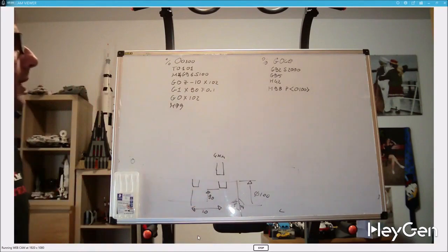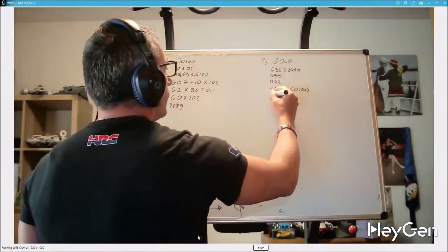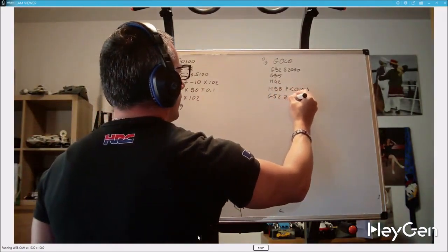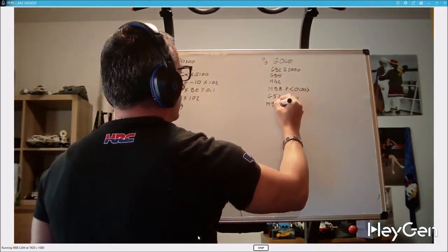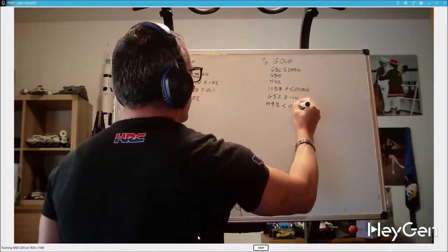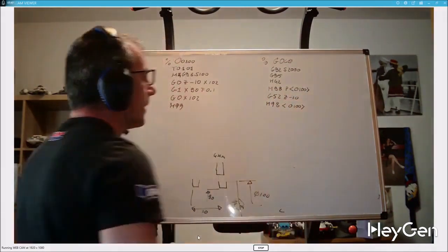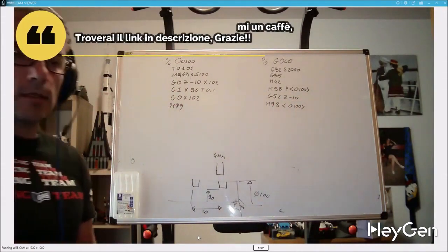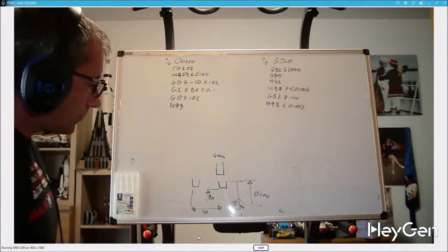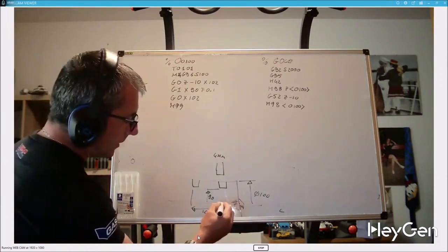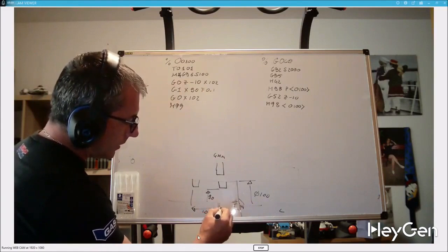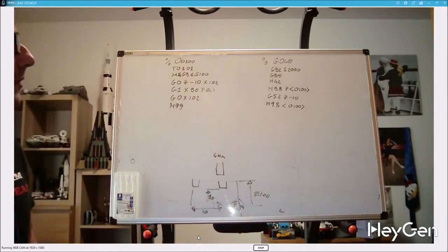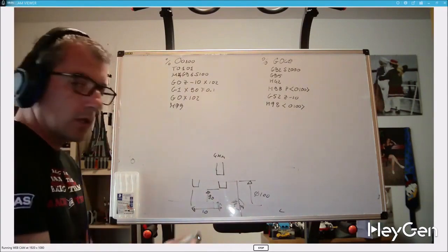So I use a function called G52 Z10, then M98 P0100. G52 Z10 is the translation of the origin. In simple terms, this origin is taken and moved 10 millimeters for the machine. The origin is no longer here, but is now 10 in the negative Z direction.